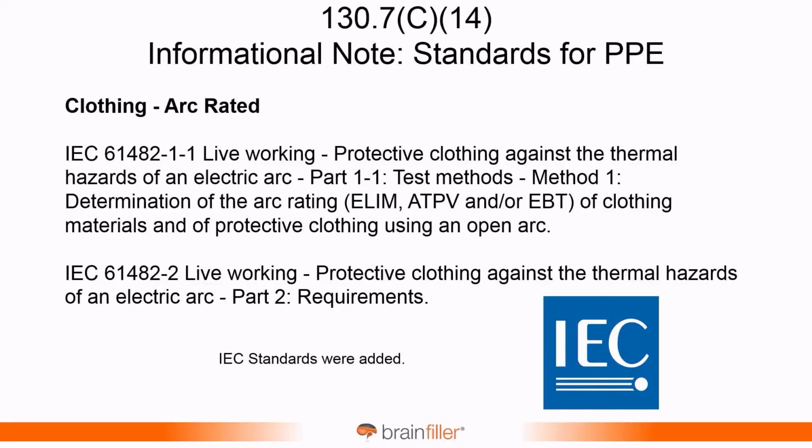And well, being chairman of all those standards, I had to put on my official IEC hat and fire back. It's like, wait a minute. IEC standards are just as good and maybe even a little more stringent than ASTM standards. But what happened along the way is, guess what? In 2021, the IEC standards have made their way into this. You notice 61482-1-1, that's the actual test method.